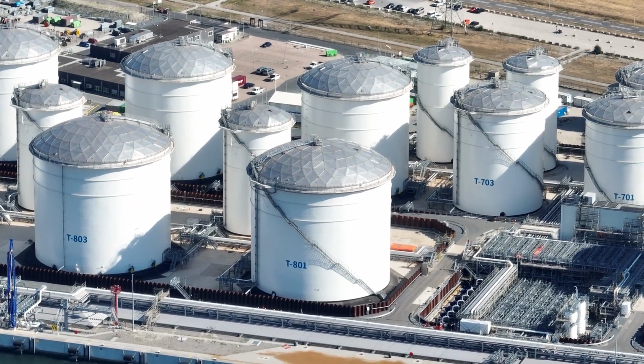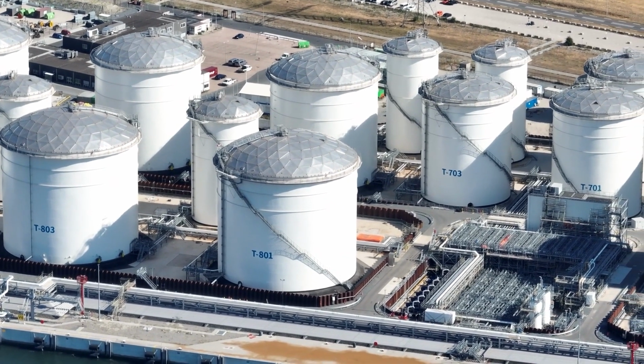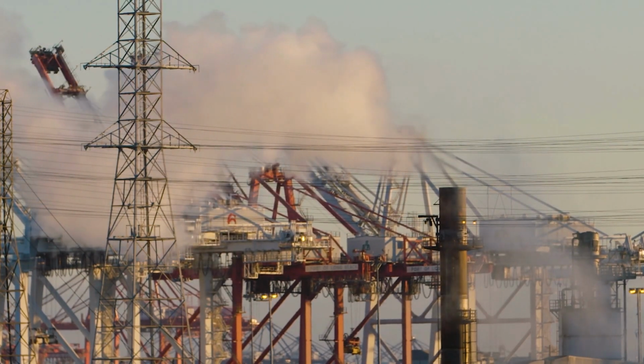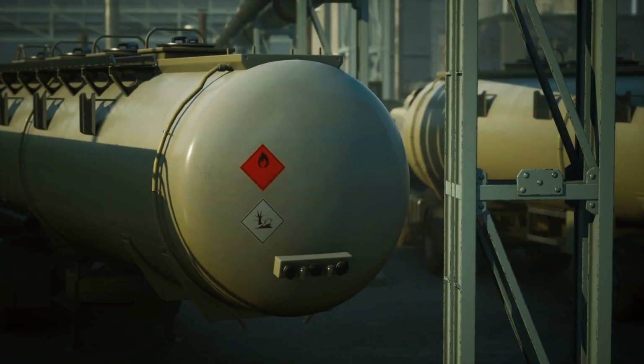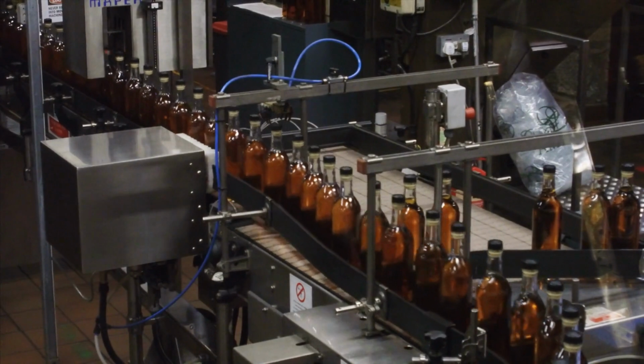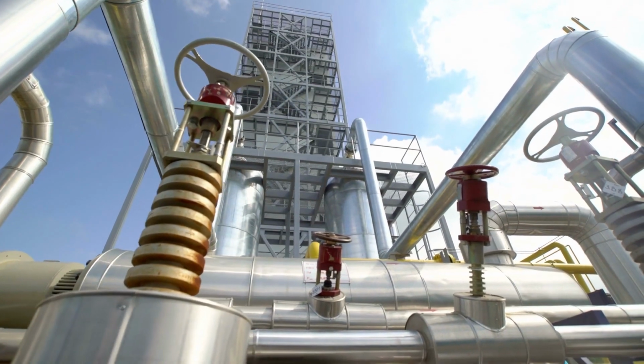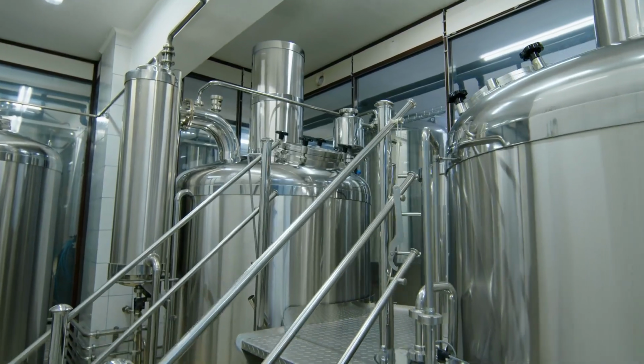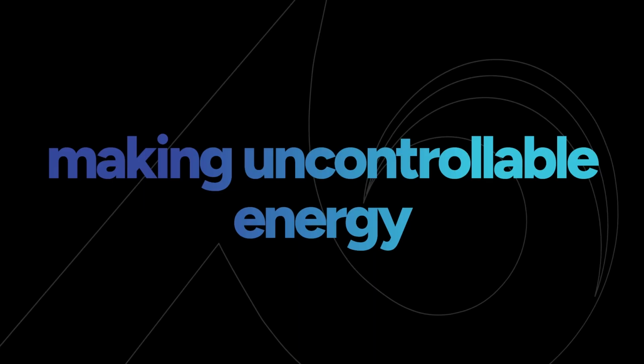The NEC divides hazardous material areas into 3 classes and discusses handling electricity specific to each area. So Class 1 hazmat areas are those where electricity could ignite airborne gases. Examples of Class 1 areas include refineries, paint shops, gasoline storage areas, and alcohol production plants. You see, these locations often contain airborne chemicals or gases that are highly flammable or susceptible to explosion, making uncontrollable